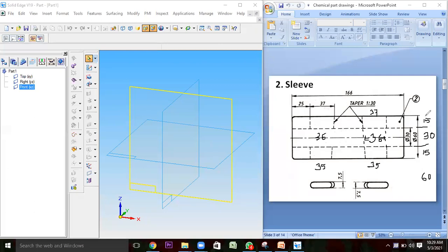So for every interval of 15 mm, the reduction of 0.5 mm will be happening. All of you understood that, right? So here 1 is to 30, means for 30 mm travel it will be 1 mm. If it is 15 mm travel, then it will be 0.5 mm. So here we are having 36.5. Okay, and here we will be having 35.5 mm. So in this way you should be doing the calculation.